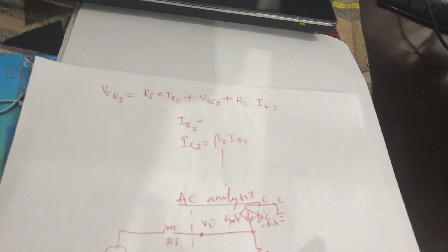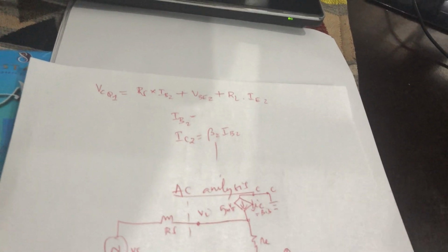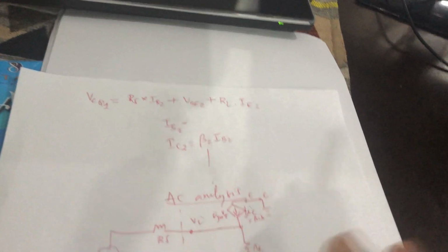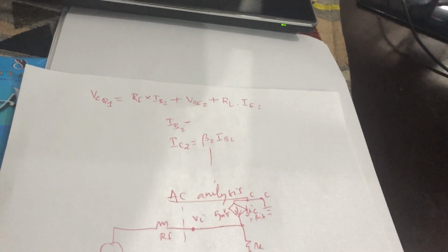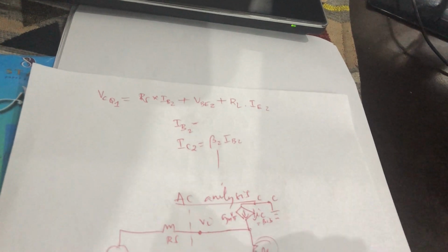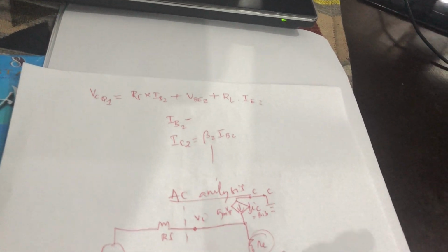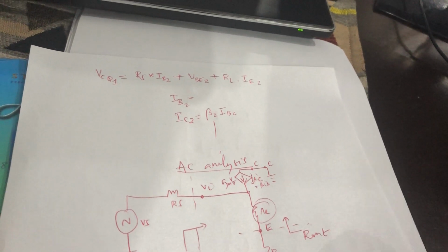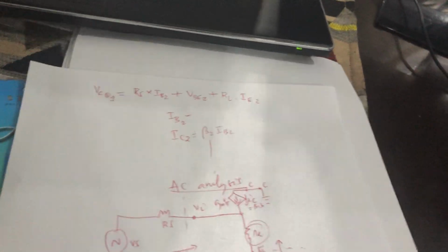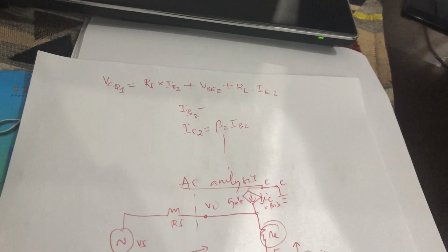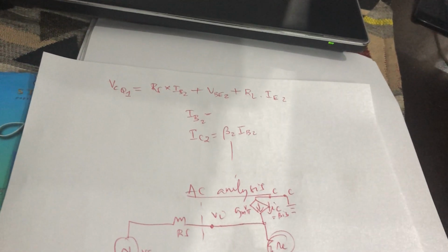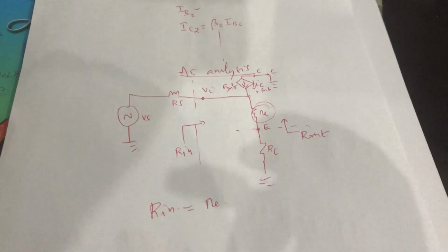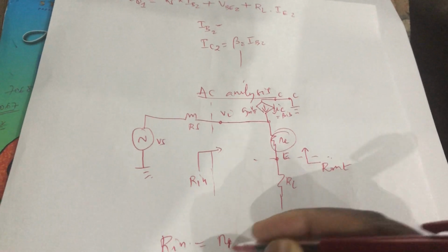Okay, so in terms of R in this case, that will be the resistance observed from that point looking into the input of the transistor, and that is nothing but RE. RE. When it comes to... it's not RE. Actually, looking into the base, you won't see RE. Let's be careful. Looking into the base, you will normally see R pi.